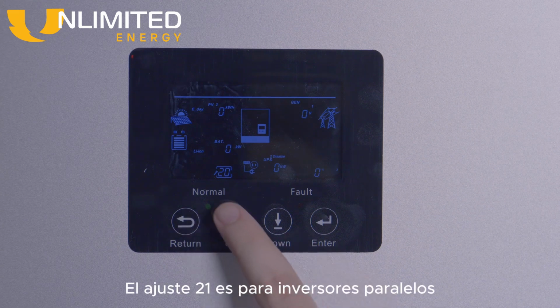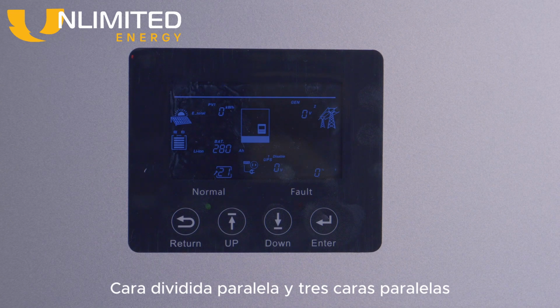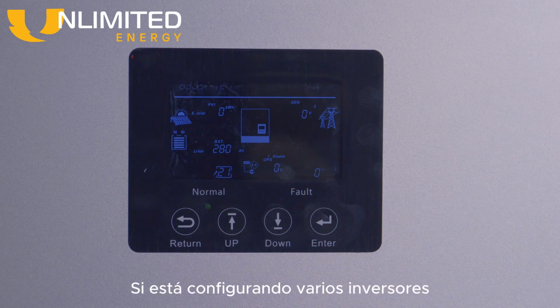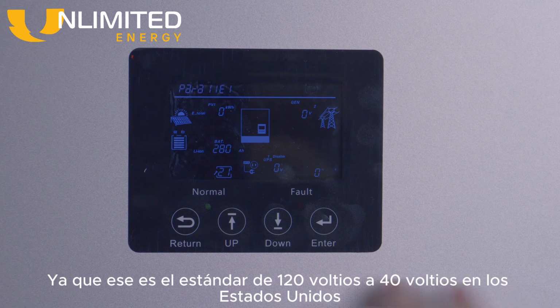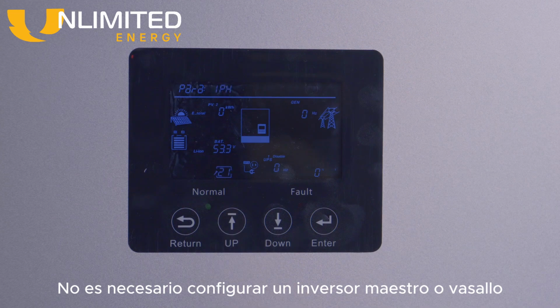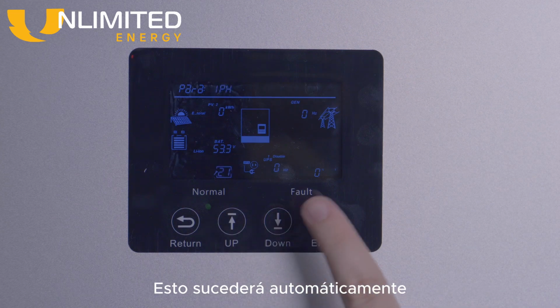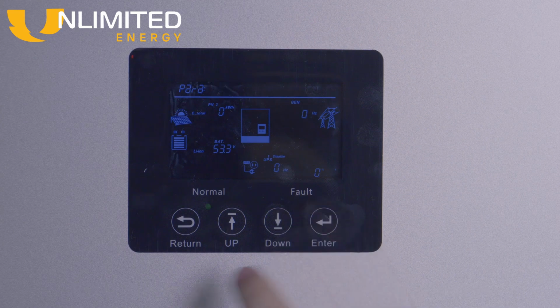Setting 21 is for paralleling inverters together. The options are no parallel, split phase parallel, and 3-phase parallel. If you're setting up multiple inverters, you're likely needing split phase parallel, as that is the 120 volt, 240 volt standard in the US. You don't need to set up a master or slave inverters. This will happen automatically by the order you turn on paralleled inverters.